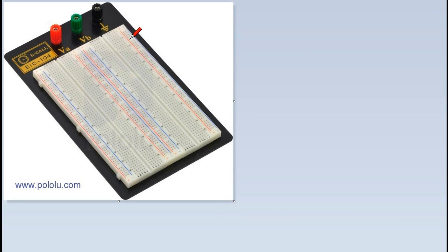It's too easy to accidentally plug something into ground that you intended for power, or something you intended for ground into the positive side, and fry your circuit. We're going to add circuit protection to our circuits to help prevent that, but I try to keep the positive and the negative, or the plus volts and the ground, on opposite sides.